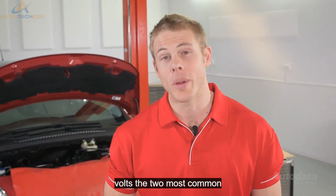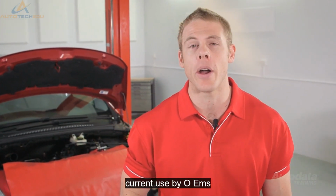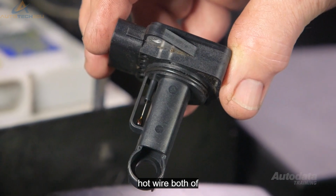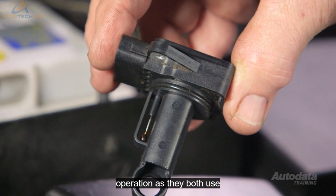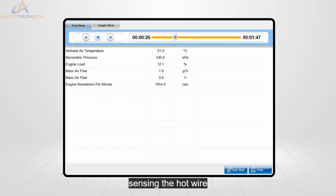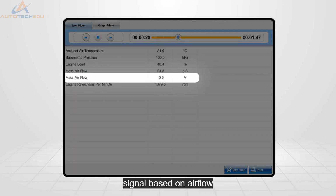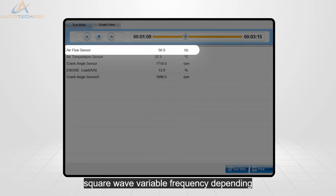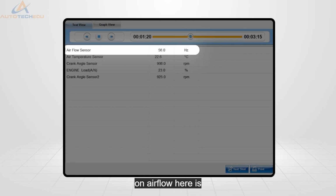The two most common types of airflow meters in current use by OEMs are the hot film and hot wire. Both of these sensors are similar in operation, as they both use a heated element for airflow sensing. The hot wire sensor generates an analog signal based on airflow that varies between 0.2 to 4.8 volts, while the hot film generates a digital square wave variable frequency depending on airflow.